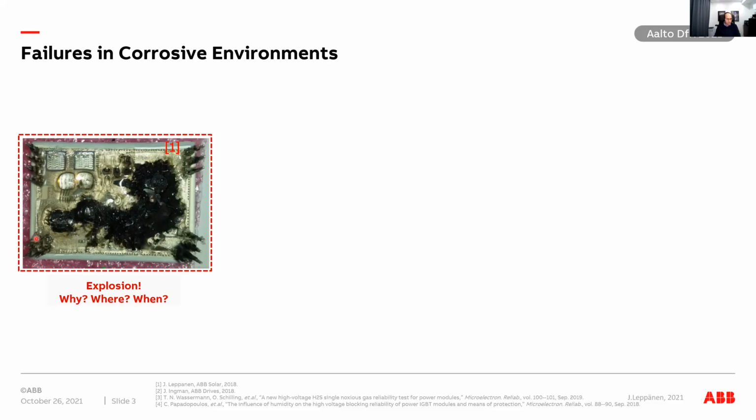But yeah, this is an open package, a very small power semiconductor package. You can have multiple of these chips here, maybe some diodes like these, and other diodes here, and then some MOSFETs here. So very basic functionalities in principle, but on the other hand, because they need to transfer really large currents and really large voltages, meaning the power densities are really large, that's what makes this so difficult. I'm not going into details about the power densities and so on, because that's covered in my other lectures.